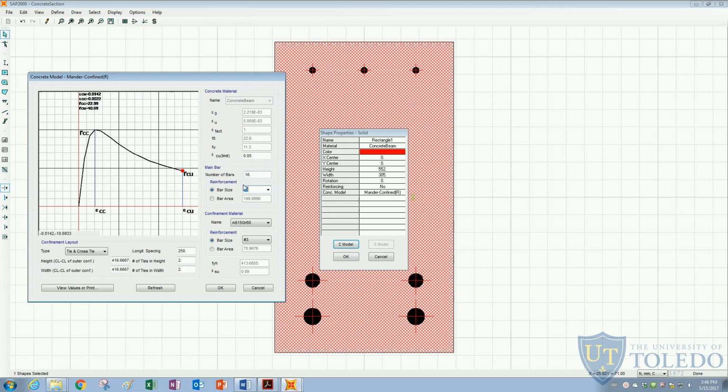But for this part, we will try to balance out the rebar diameters that we have here to make SAP2000 do the correct calculation based on our reinforcement layout. Our maximum diameter is 30 and our minimum is 10, so I'm going to put a 20 bar, and we can see that the longitudinal reinforcement does not play a very important role in the stress strain response diagram here.